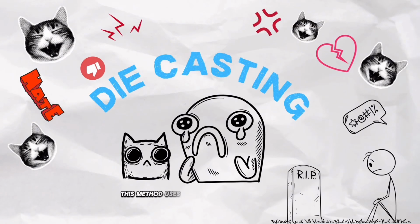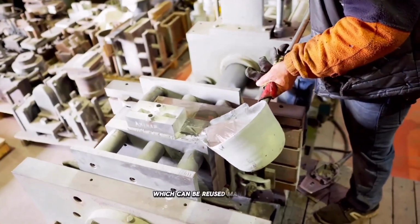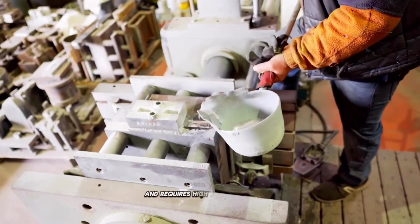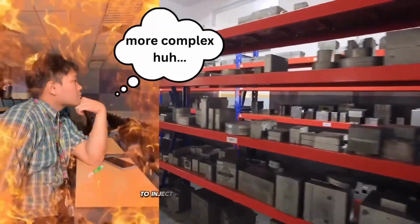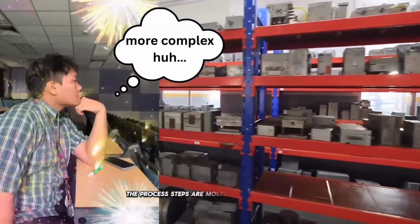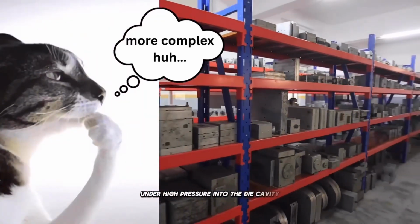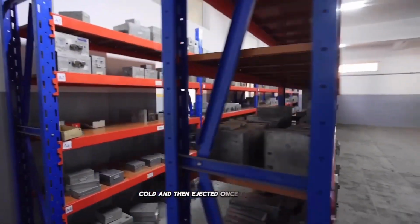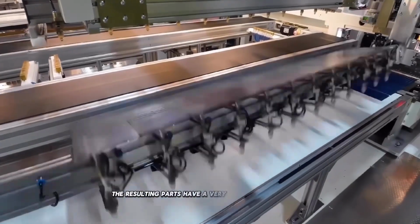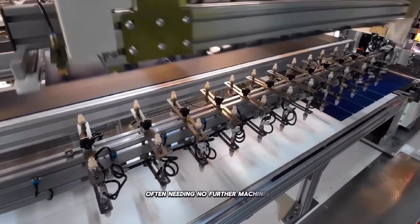This method uses a metal mold, also called a die, which can be reused many times. Die casting is more complex and requires high-pressure machines to inject molten metal into the mold. The process steps are: molten metal is injected under high pressure into the die cavity, cooled, and then ejected once it solidifies. The resulting parts have a very smooth surface finish, often needing no further machining.